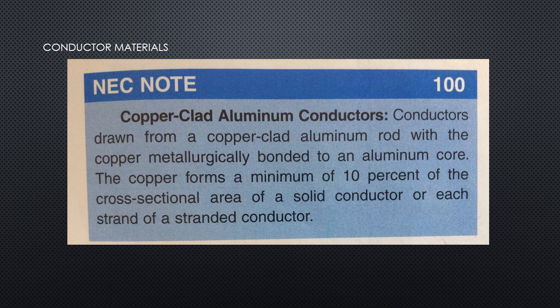Aluminum is a good conductor, but must be installed with additional care and preparation. Aluminum must be cleaned just prior to terminating due to the rapid oxidation of the freshly exposed surface. Exposed aluminum at terminals should be coated with an antioxidant. In addition, aluminum connections tend to deform and loosen more than copper connections. If installed properly, aluminum conductors are dependable and economical.